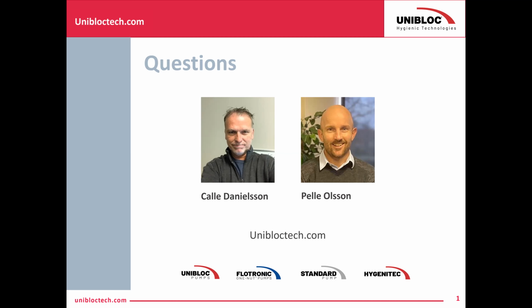Yes, you can. Some industries tend to do that. Most don't. The reason why you don't do that is because you will have to oversize the lobe pump in order to achieve that higher flow rate for the velocity. And that becomes a little bit more pricey. So that's where you use a booster pump instead.